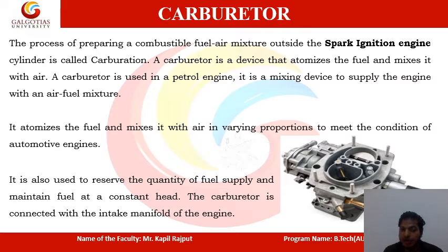A carburetor is a device that atomizes the fuel and mixes it with air. A carburetor is used in the petrol engine. It is a mixing device to supply the engine with an air-fuel mixture. It atomizes the fuel and mixes it with air in varying proportion to meet the conditions of automotive engines. It is also used to reserve the quantity of fuel supply and maintain fuel at a constant head. The carburetor is connected with the intake manifold of the engine so that it can send the fuel.